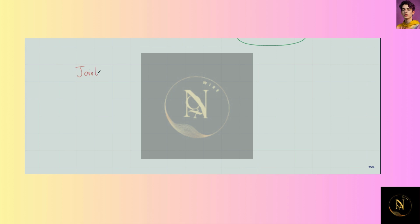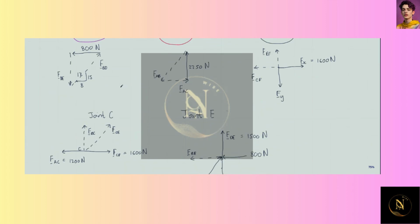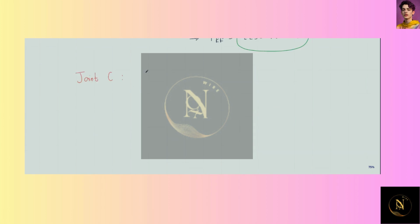Next, we'll look at joint C. If we go to our free body diagram for joint C, which is circled here, we can again look at horizontal and vertical components. If the right direction is positive, the sum of the forces in the x direction must equal 0.